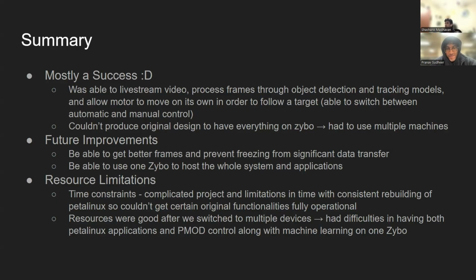However, we couldn't produce our original design to have everything on one Zybo. We had to use multiple machines. So in the future, what we would like to do is host it on one main machine rather than have three separate devices. Another issue was that we weren't able to get better frames, and the stream would just freeze after around 30 seconds to a minute, due to some buffer issues. We couldn't fix that and would like to fix that in the future.